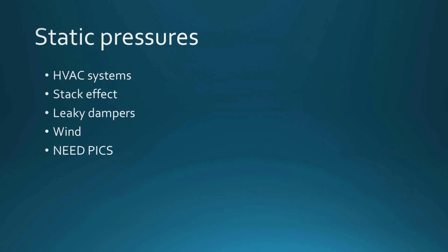So another thing that we have to determine when we're trying to figure out hold time or peak pressure is what's happening with the HVAC system, whether there are any leaky dampers that could be sucking agent out of the room, what's happening with wind. I recall once there was a discharge test done on the telescope in Hawaii, and they discovered that all of the agent on the windward side of the building was lost in seconds, so wind was the driving force.